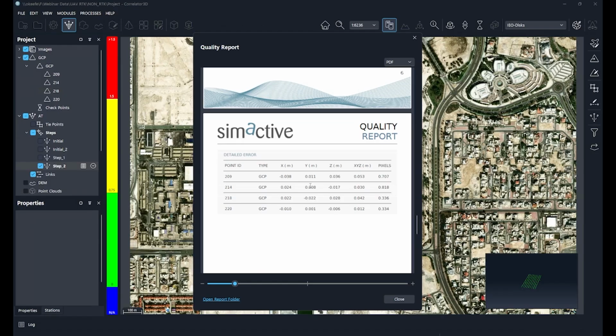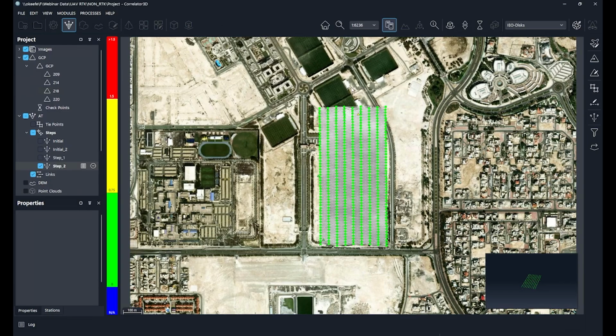Now, what was the other alternative I was thinking about? Well, it's in a well-populated area. Again, go to the county files and look for some publicly available lidar. I've gone through several websites and tools, and they sometimes provide a DSM at certain resolutions. Even better, you might get a point cloud of this specific area and then import it. And then you can create your own GCPs.